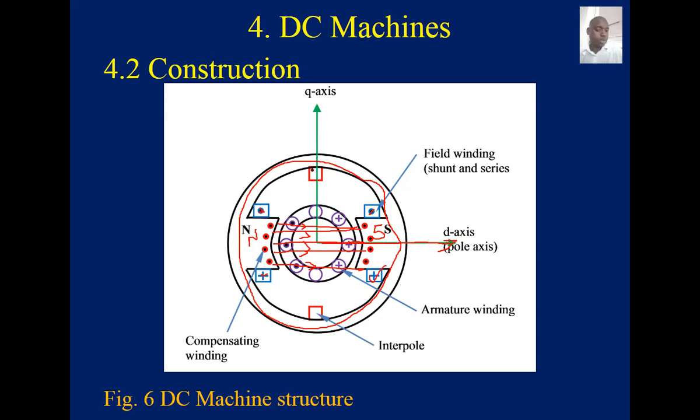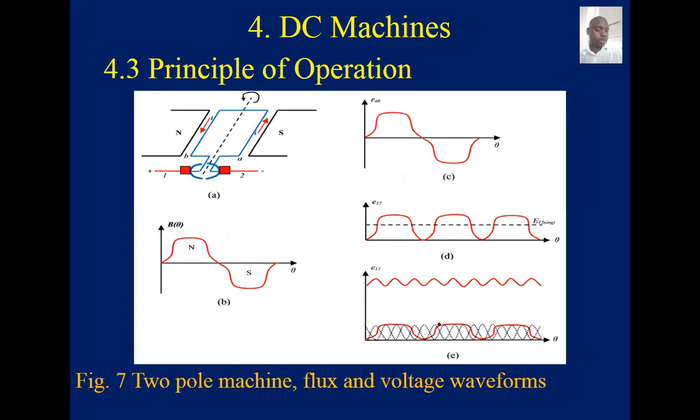And then this midpoint between poles, we normally call it the interpole. That means we expect no overall electromagnetic induction on this line. That's why you see that they are blank. That will be the interpole. We'll refer to it later when we talk about commutation and other stuff.